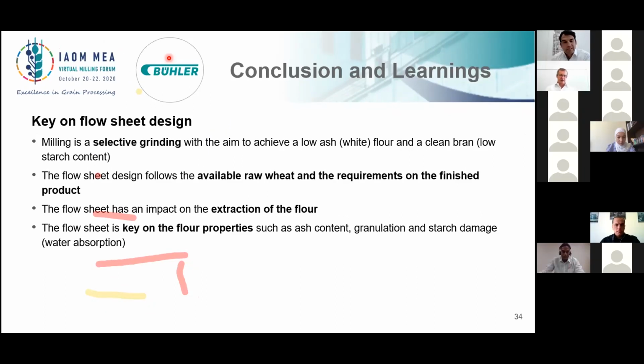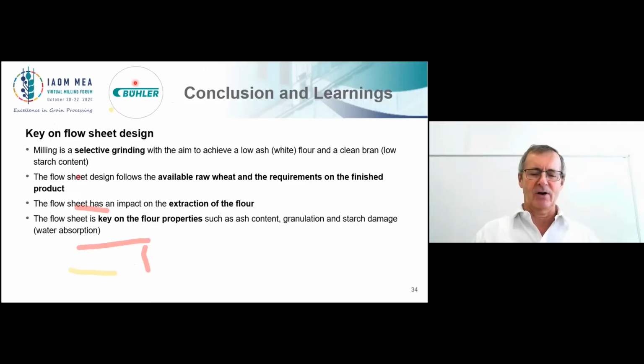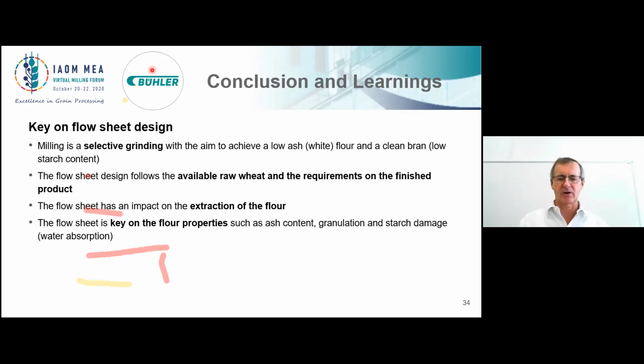Yes, we can say, but on the soft wheat and purifiers, they don't like each other. The soft wheat, first of all, you don't get a bigger amount of semolina. And secondly, the purifiers always build up some flour attached. So it's not always easy for a real proper soft wheat to pass through purifiers.